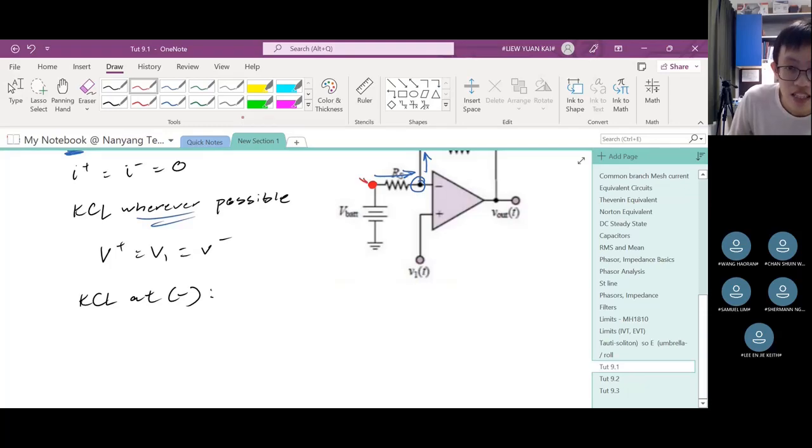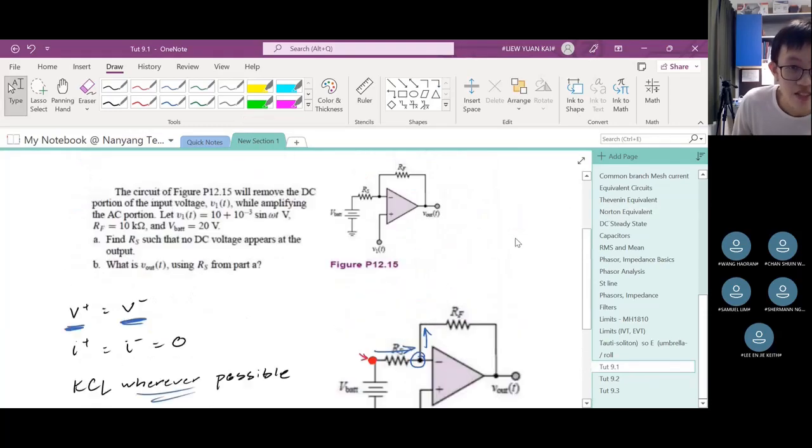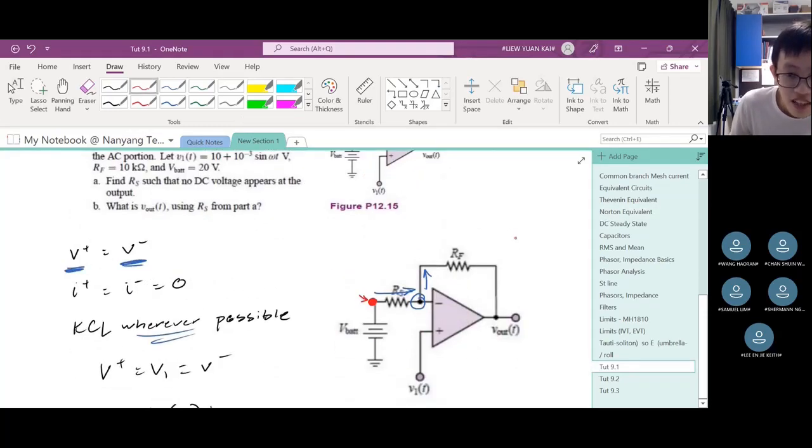So what is the value of this node? The value of this node is given by the V battery, correct? Because down here is ground, which is 0. Then you cross V battery. This potential difference is V battery. That means up here must be V battery, correct? This is the negative terminal. This is the positive terminal. You climb up towards a higher potential. So up here is V battery. You just label it V bat.